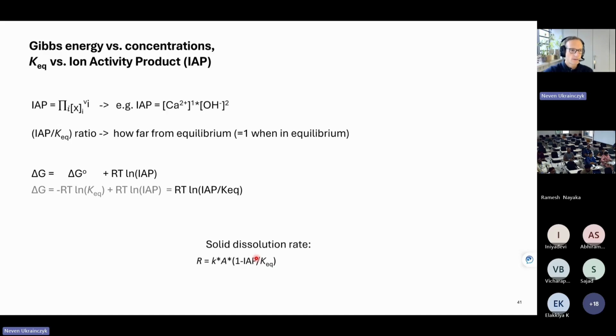Then you have oversaturation, and when you start to have nucleation, you start to precipitate the hydration products, and then cement clinker can again dissolve. That's why we also have setting time: during the setting time you have too much oversaturation because you need to form the first nuclei, and later, when the first portlandite is formed, then you start to nucleate.